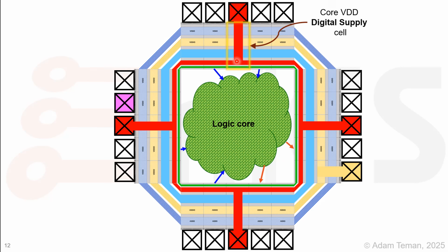That's the same thing, but it connects to the core VDD ring. And we also have a special cell that connects to the POC ring that we had before, so that's going to connect to this green guy over here. It's also connected to our VDD IO, but it connects to the POC ring as well. So those are our power domains and our power supply cells.